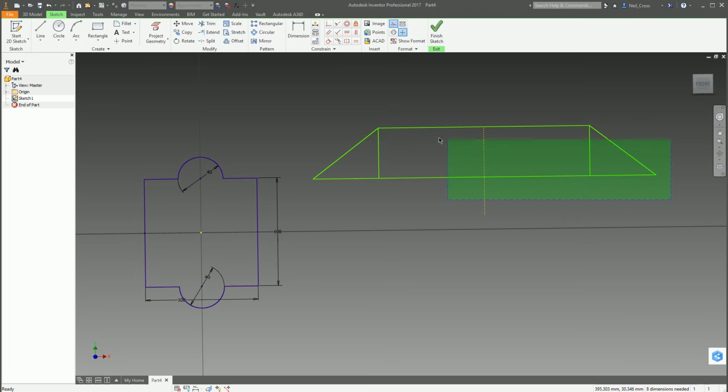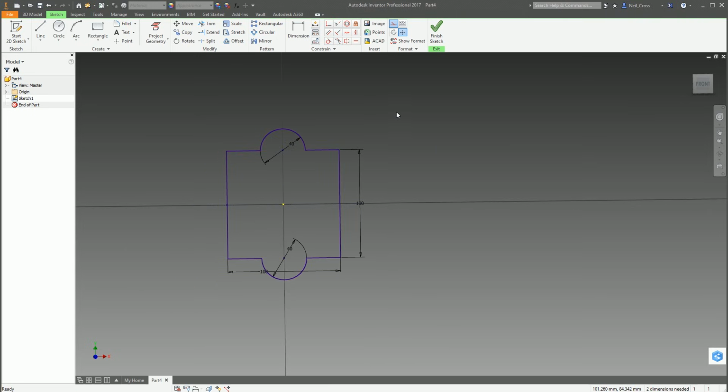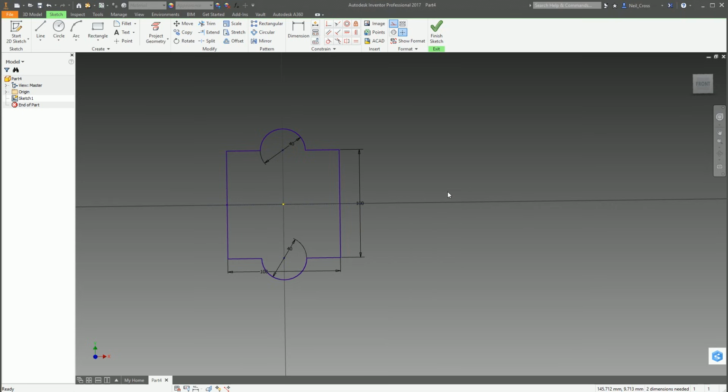And that's, again, useful for a whole bunch of things. Not limited to just that scenario. There's all kinds of different scenarios you can use these constraints for. They are indeed applicable to anything that you can sketch. So I am showing some very limited examples here. But that's the symmetry constraint. Some of the things which you might find useful. Let's just get rid of this sketch.